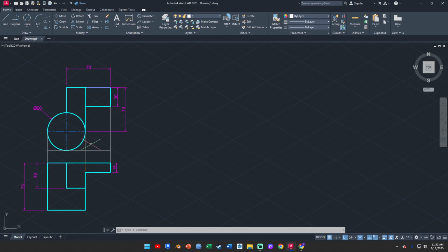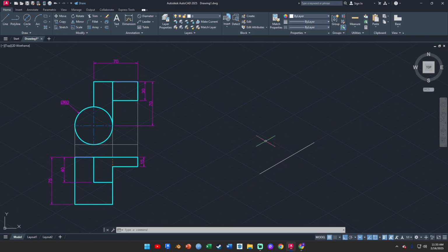And seeing that we're constructing this with x being the lowest point, we're going to want the front view to be on the right plane, right? So we're going to put our 100 mm on the right receding axis or the right plane, going towards the right. And when you change the isoplane top, please make sure that you have ortho mode on, or this line would not be the 30-degree line that you want it to be, right? So we have one length there.